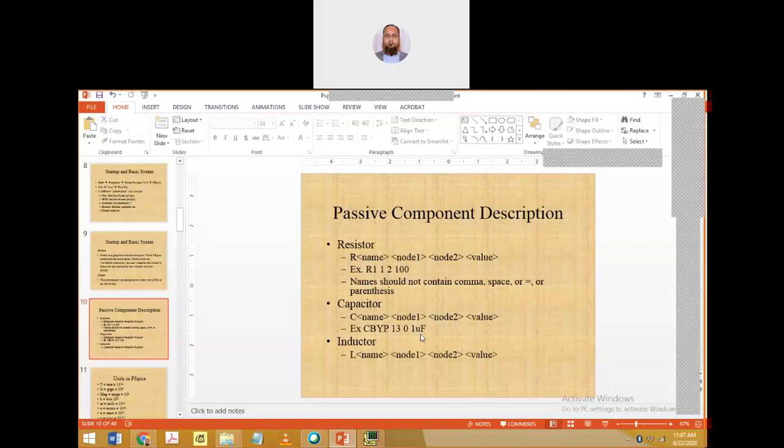Here you remember that we have written U, because there is no standard micro sign, so U is used directly to specify micro. If we write F, it will understand. Even if you don't write F, it understands that it is a capacitance, because by default the capacitor unit is farad.